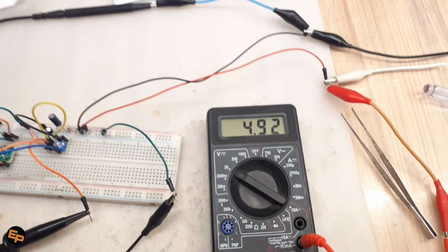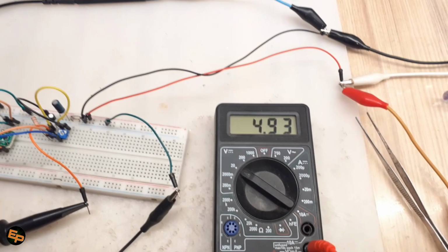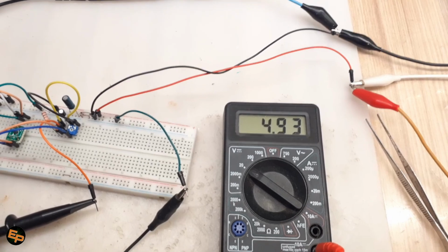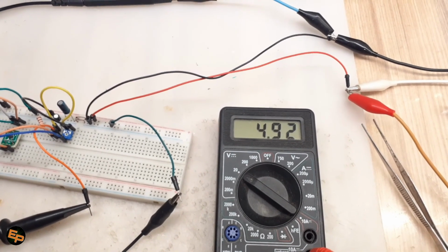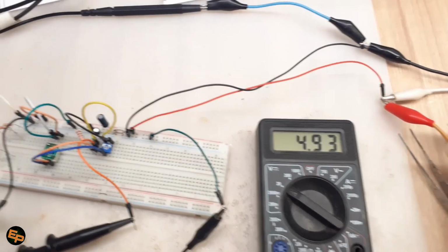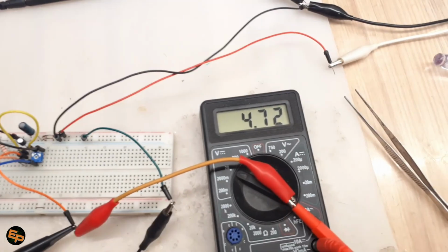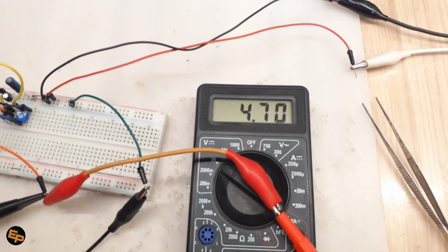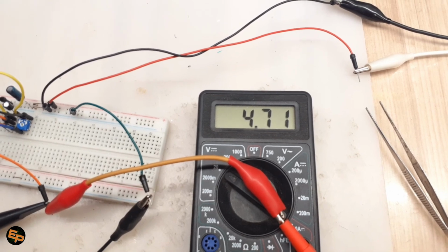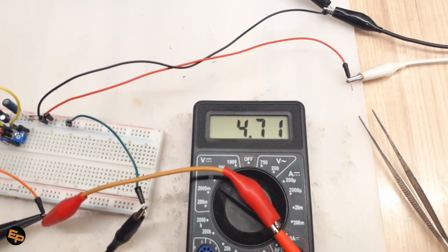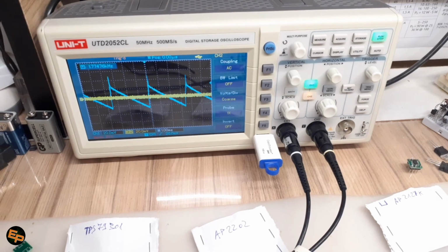And then I basically measured the input voltage with a voltmeter. I wrote that number down in the table, and then I connected the voltmeter to the output and measured the output voltage. The difference is the so-called dropout. Okay, so this is at 50 milliamps.